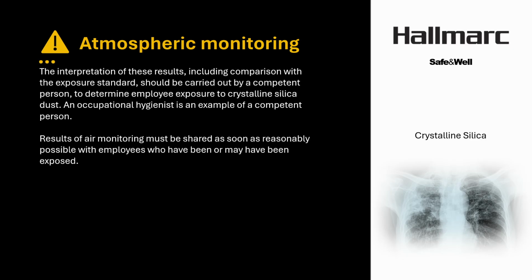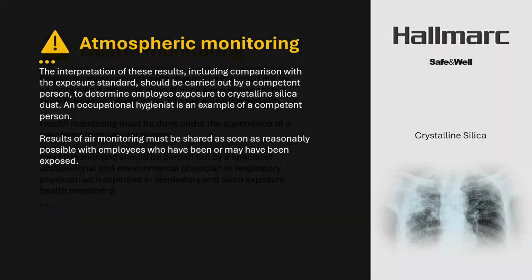The interpretation of these results, including comparison with the exposure standard, should be carried out by a competent person to determine employee exposure to crystalline silica dust. An occupational hygienist is an example of a competent person. Results of air monitoring must be shared as soon as reasonably possible with employees who have been or may have been exposed.